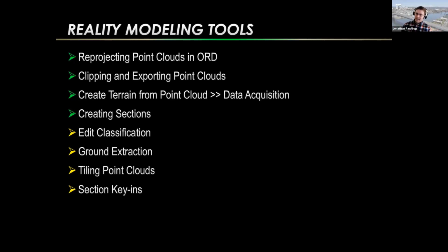We will then look at what we referred to in V8i. In InRoads V8i had a tool called data acquisition. That same tool is available in ORD. No longer called data acquisition. It's called create terrain from point cloud. So we will look at that.